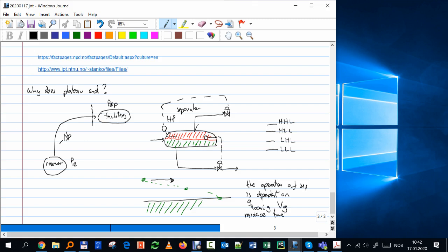And that is the same for many other components we have after. We have compressors, we have pumps, we have many things. So if we start changing that pressure, we are affecting the proper operation of everything else downstream. Okay, which process engineers are terrified. If you are planning an EOR, let's say, oh, I can get a very nice rate if I lower that pressure, you're going to get screamed at quite a lot. No way, we cannot, no way. Okay, it's actually a big exercise. You have to check if you change that pressure, your volumes will change,